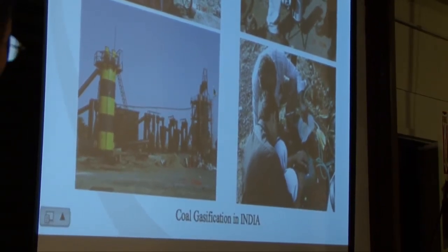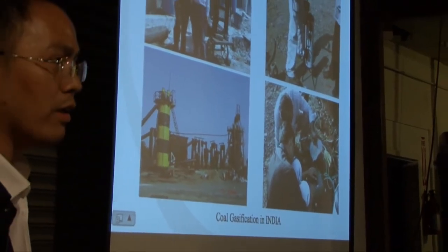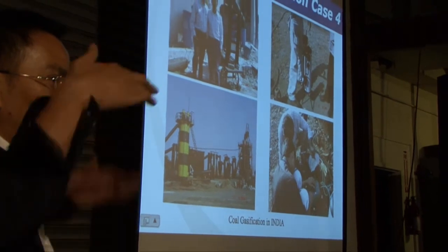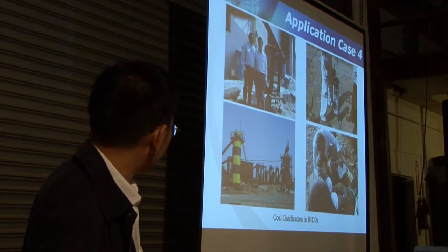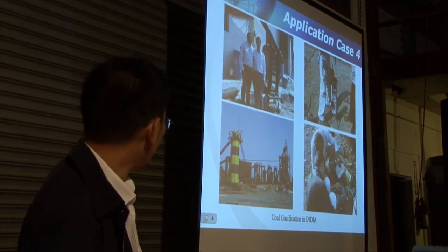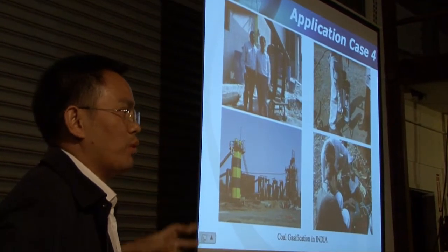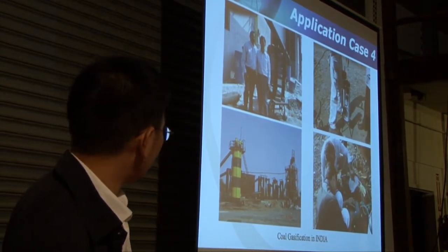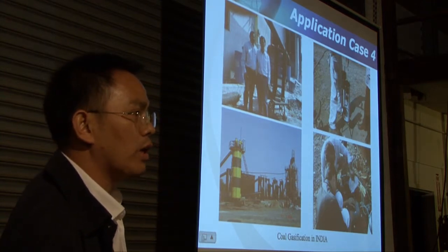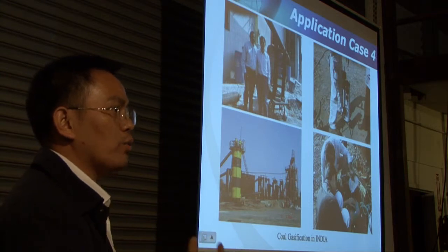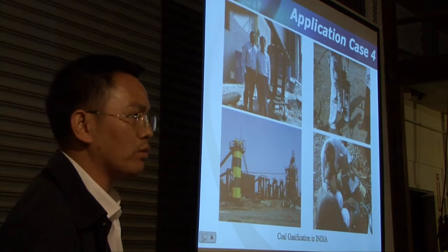Generally, this is a gasifier, and then the dust, and here is the ESP for tar removal with electricity. So here we monitor the gas and also the oxygen. Is oxygen more than 100%? Then explosion. This is a big problem. So monitoring oxygen is very important. Also the gas composition. The gas goes out here to the combustion for ceramic. So this is very important for the gasifier and also very important for the combustion.